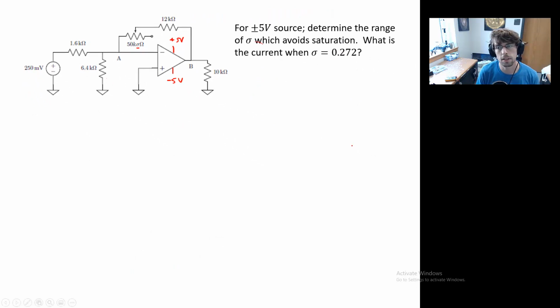Now for simplicity, to see if we can get a sense of what's going on with this amplifier, we just stop and ask ourselves if maybe we have some idea about what this thing's going to do. We notice that the non-inverting input is to ground. And so we expect that whatever comes out, it will be inverted. So we'll probably end up with a potential less than 0. Okay, that's the first thing.